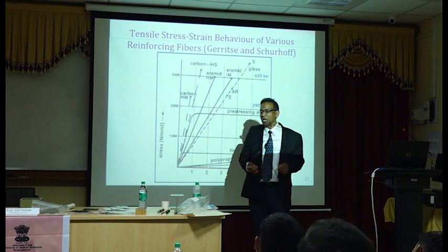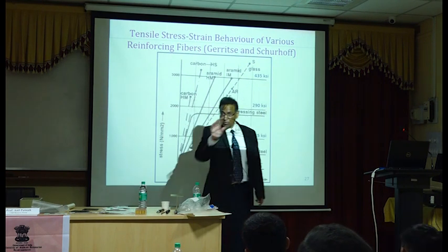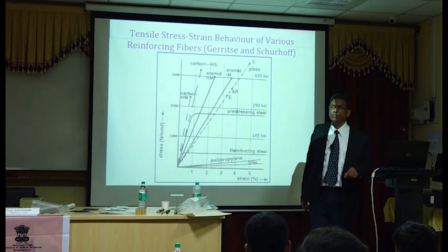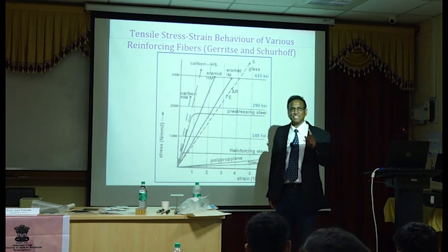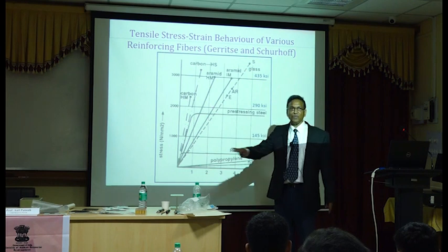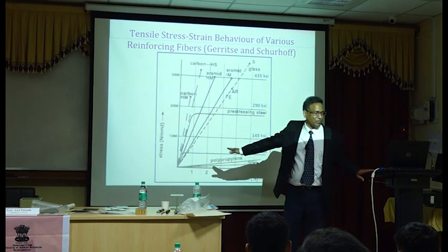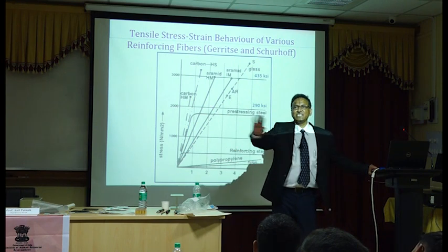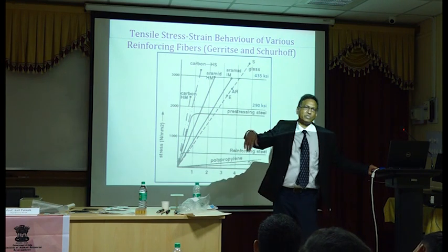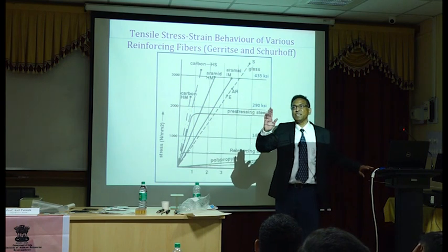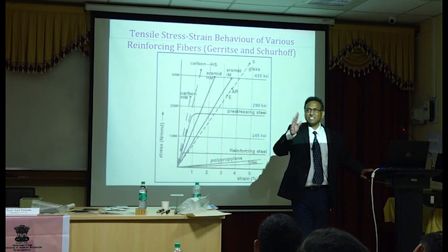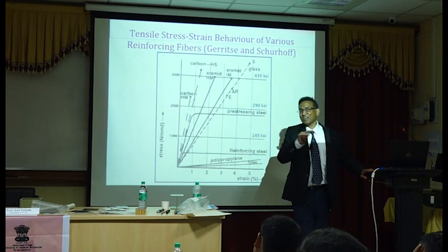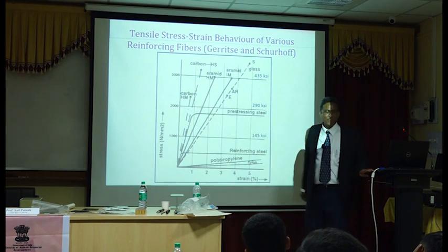So that's the problem. If any one of you wants to develop a good FRP bar or FRP material, one thing you want to look at is stiffness. Strength, towards the end of this course, you'll see strength is not a problem. High strength, low strength, it doesn't matter as much as the modulus. If you have high modulus, you can utilize the strength better. That will be more obvious when we do the actual flexural analysis.